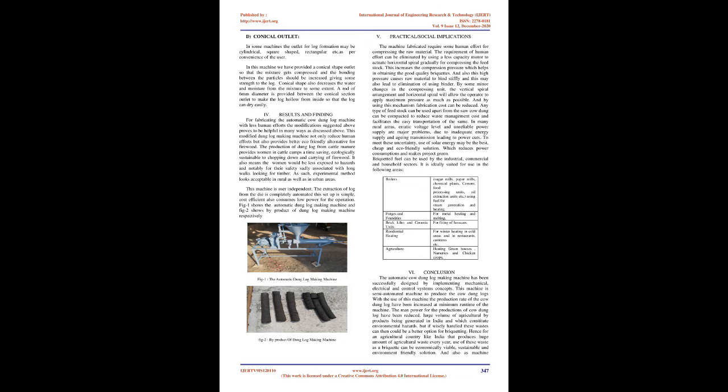A bevel gear arrangement is used to take the power from the gearbox. Bearings are used for free rotation and to lower the friction. When the mixture is mixed with coal or clay or other binders, it is poured inside the hopper. The mixture is mixed with the help of the mixing blade and the mixture slides down into the grinding unit.